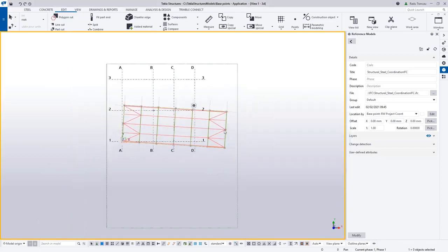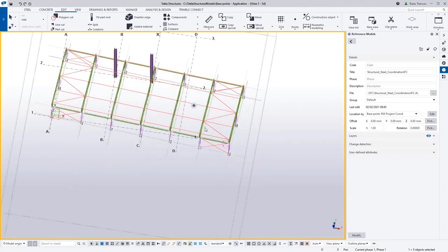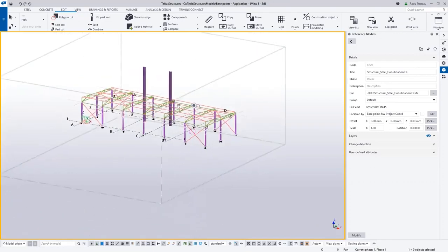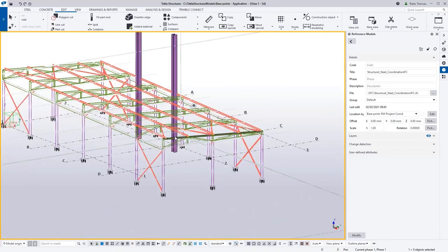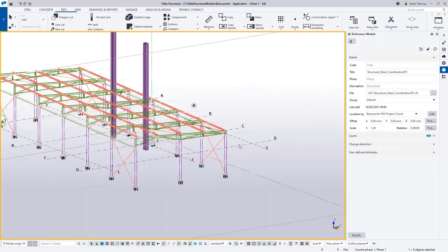Okay, so these are the three methods of figuring out how to bring the IFC closer to the origin. I would recommend you do that first before starting modeling, as whenever you start adding new objects to the model, it will be very, very difficult to start changing the coordinates from that point. So if you have the chance to do that as the first thing in the project, that will save you a lot of time in rectifying other mistakes along the way.